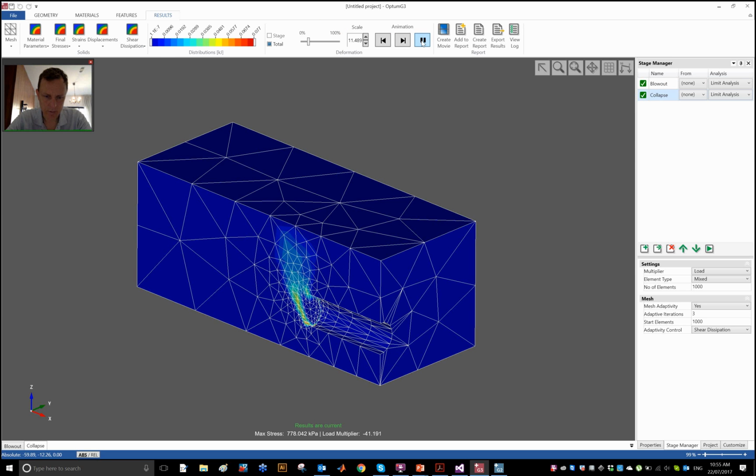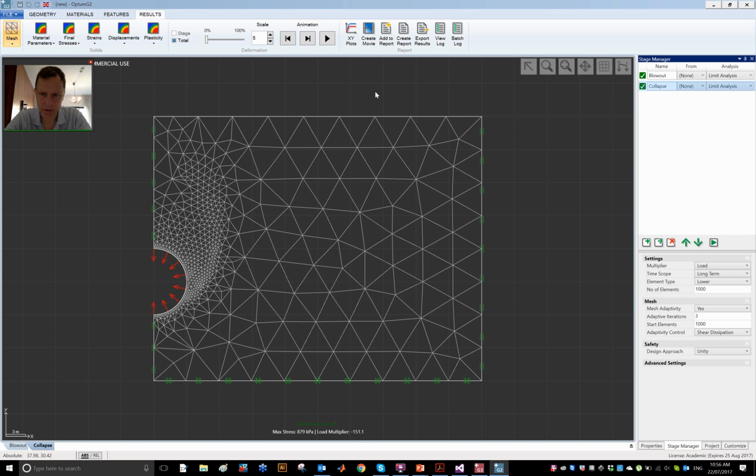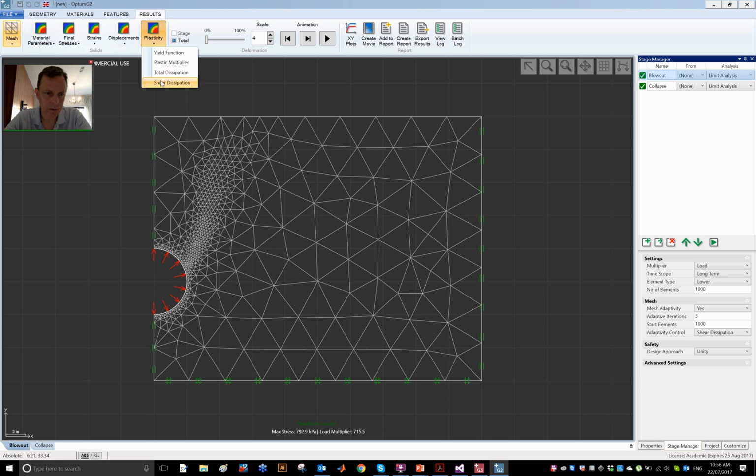In this case, only about 41 kPa necessary to prevent this thing from collapsing. So 41 kPa necessary to keep the tunnel face standing up. So you want to be in between those two pressures, 41 and 2800. And let's just see what the 2D analysis gave.